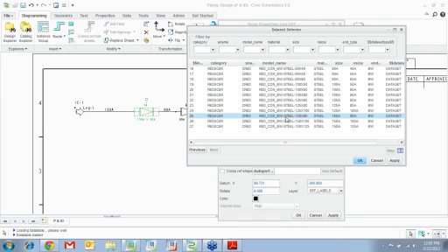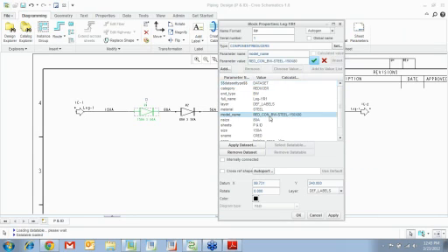This is the name of the Pro E part that it needs to use. So this is like a data set that you can fill up in Excel and you can load it one time and that's it. You never worry about it again. So you just go apply a data set. I want to go from size 150 to size 80 and you hit OK. It will automatically fill the model name parameter for you.